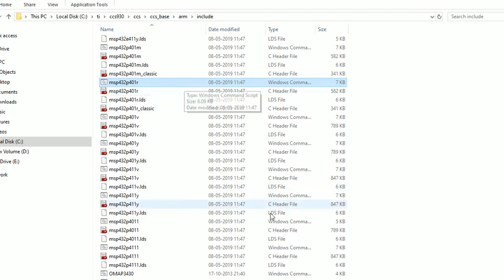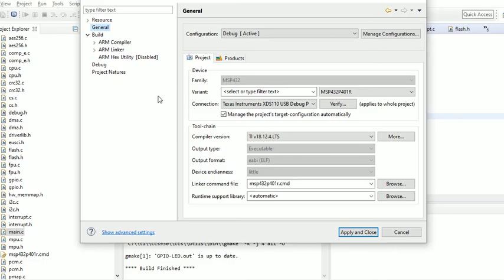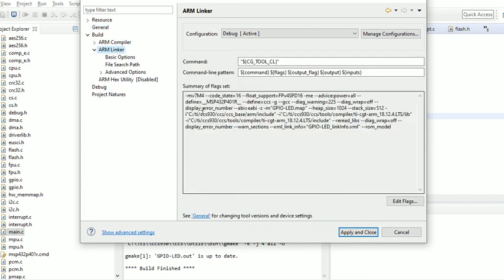Going back, if you see the linker options, these are the actual flags that are set. You can see the heap size, whatever the program needs, and the microcontroller which needs to be used, all are mentioned here. If you see this, define is equal to underscore MSP432.